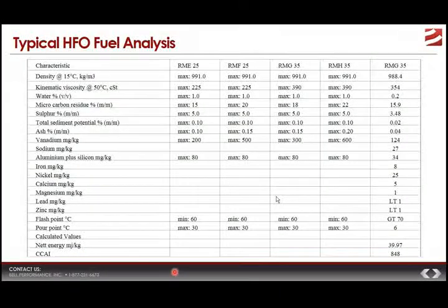You've got sulfur content. Sulfur content is specified or capped for environmental reasons and also to prevent corrosion. The maximum sulfur content for fuel that's used in the open ocean is actually not 5%, but it's actually 3.5%. That changed. Contrast that with when the ship gets into designated specific areas that are closer to populated areas or closer to port.